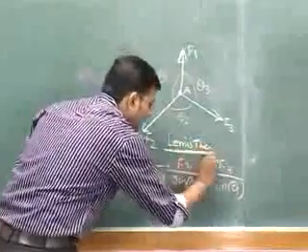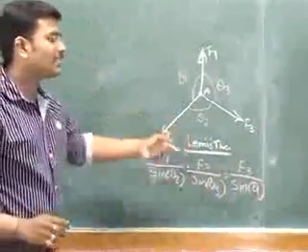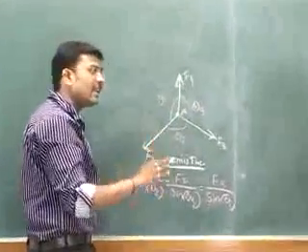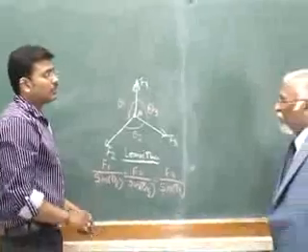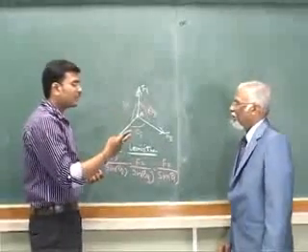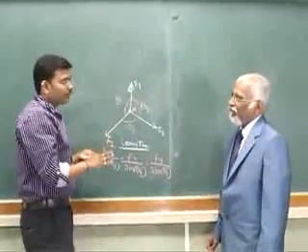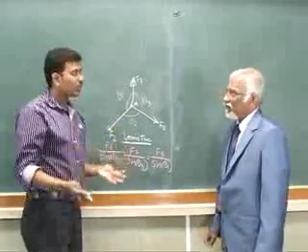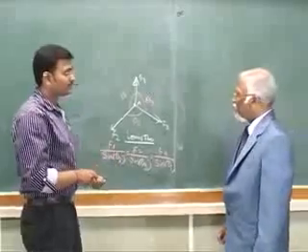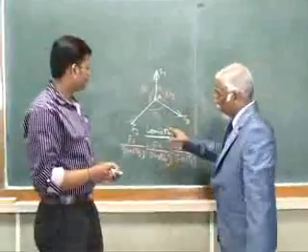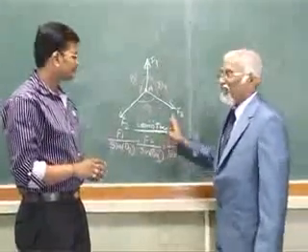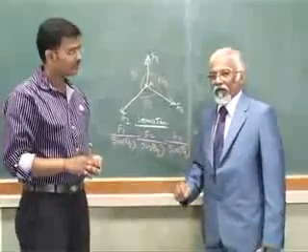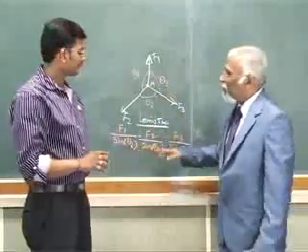So it is also called the sine rule or Lami's theorem, and this is applicable only when there exist three concurrent forces. If you have two concurrent forces, then the law of parallelogram. Three forces, then Lami's theorem, and more than three forces, then you have to go for resolution of the forces. Raviraj, it's very fine that you have tried to explain Lami's theorem. In fact, it's the sine rule, which we might have studied in 10th and 12th. Yes, sir. So the same sine rule we are applying over here.